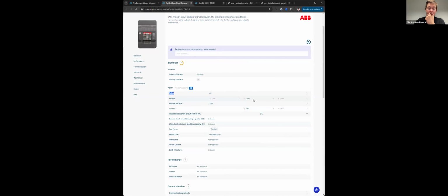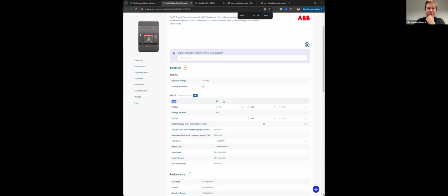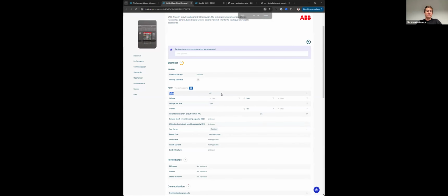Yeah, so when you're selecting circuit breakers, which is kind of a science of its own, you indeed gotta start with the voltage of the circuit breakers. I mean, typically these DC circuit breakers have multiple poles that are connected in series. Why do you have multiple poles connected in series? Because as soon as you start interrupting the current, an arc will emerge.